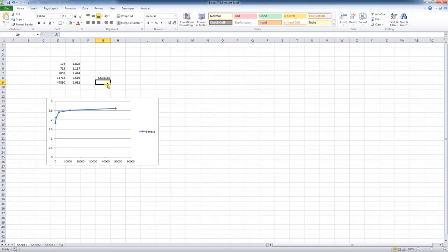Now here's another thing to be careful about. The mesh that we're going to optimize is only going to be optimized for loading in the vertical direction. If we come back later and we put another load, maybe in the horizontal direction, on our plate with a hole, then we may have to go back and check our convergence results for our particular finite element mesh.